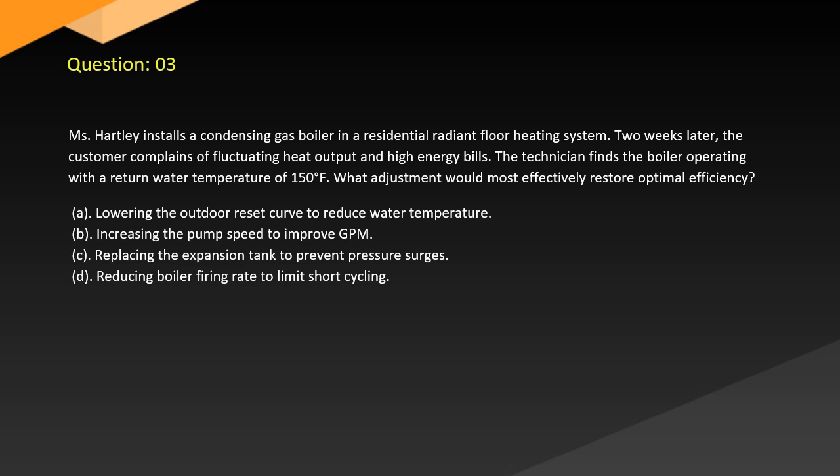A. Lowering the outdoor reset curve to reduce water temperature. B. Increasing the pump speed to improve GPM. C. Replacing the expansion tank to prevent pressure surges. D. Reducing boiler firing rate to limit short cycling.